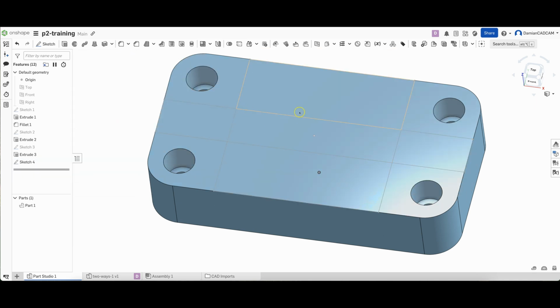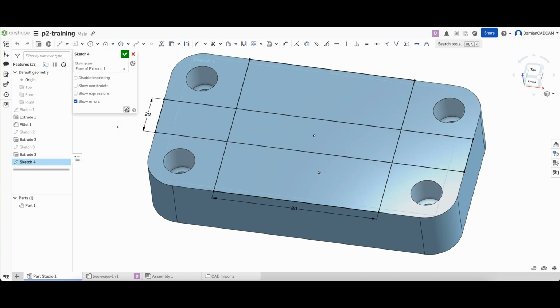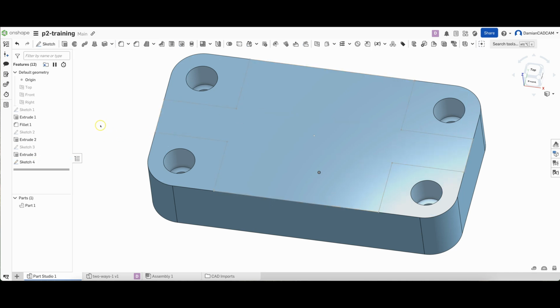Alternatively, I will show you now how to edit the sketch and how to make this sketch one single area. To edit the sketch, we go to Sketch Editing. We double-click the sketch with the left mouse button. And here we simply need to trim the geometry segments. We have the trim command, and we select the geometries we want to trim, and then we close the sketch. And in this way, we introduced changes in the sketch. This is how you can edit sketches. You simply double-click the sketch you want to edit, and now this area is a single area.